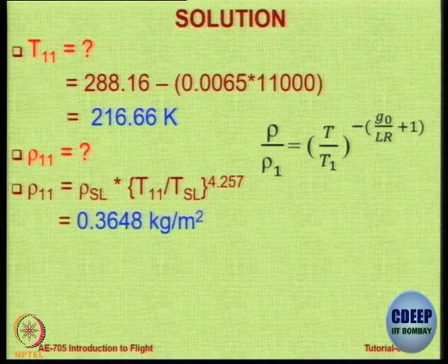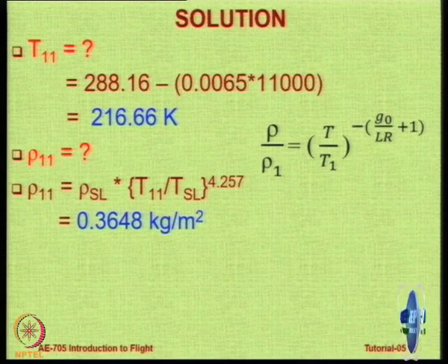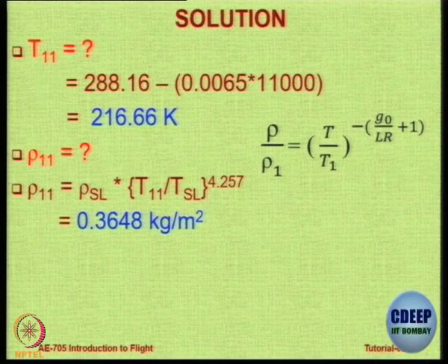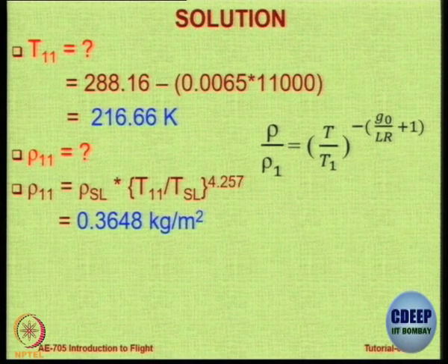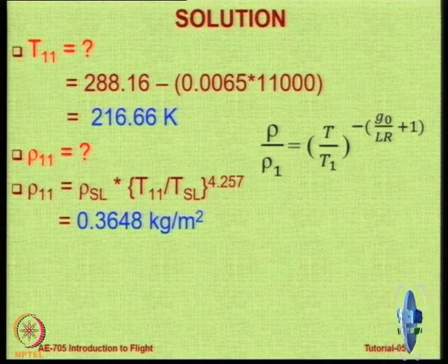Did you attend the first lecture on atmosphere? So I clarified to you that the forces and the loads acting are a function of temperature. So if the density changes, then the dynamic pressure will be different. So then the whole calculations will be different. So if you are told that operations are happening at a condition of ISA plus 20, you cannot use ISA numbers, you will get wrong values. See, the atmosphere at a place where we are flying is not equal to ISA. In the questions in the classroom textbooks, we assume ISA for ease in calculation. Okay?